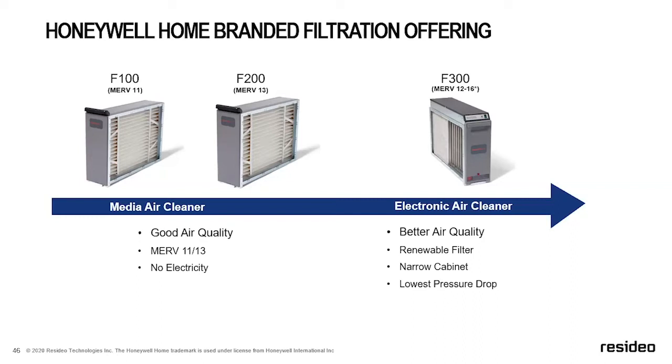And one thing you want to look at, especially nowadays, MERV 11 can capture different things: dust, pollen, some bacteria and things. MERV 13 is going to also capture those, but in addition, do a little bit better and also be able to capture some virus carriers.